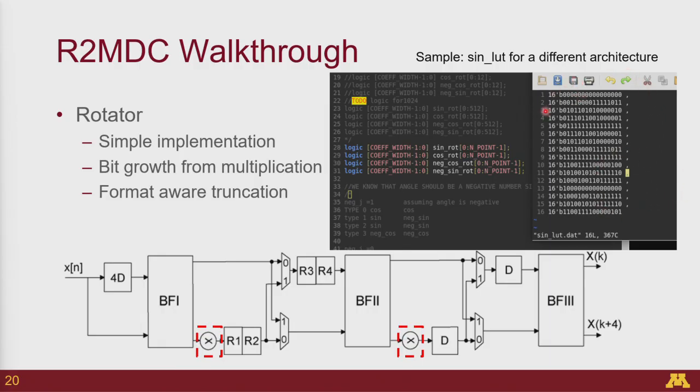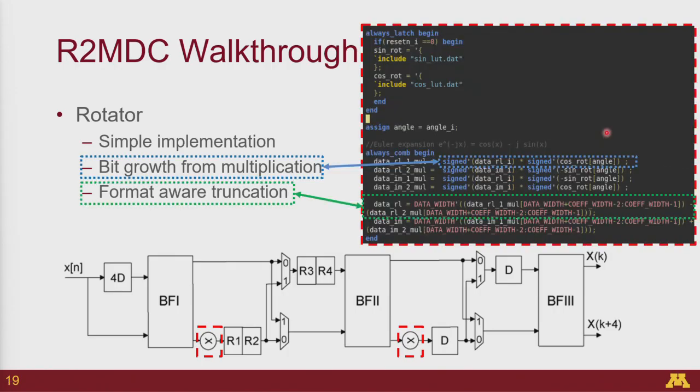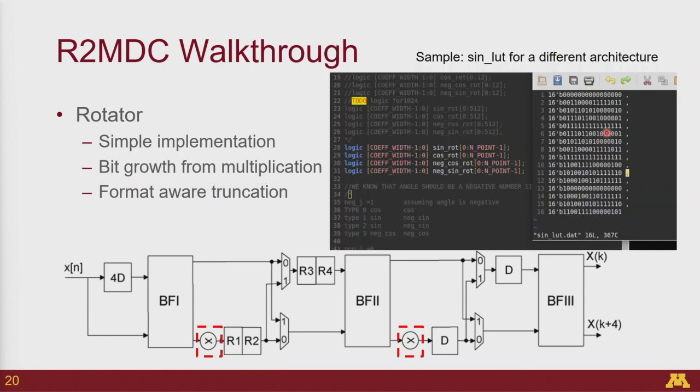So yeah, this is essentially what these lookup tables look like. And in terms of format, all this include block in Verilog does, you can think of it as text replacement. So if you were to replace the text of that file directly in this file, how would it need to look like? That's essentially the format you need to store that file in. Does that make sense?